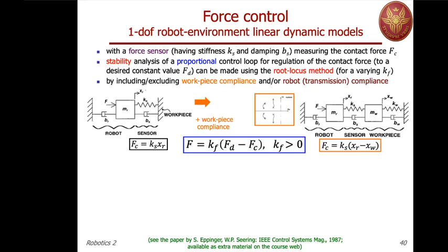So when you're now closing the loop, these four poles, which are all asymptotically stable in the open loop, will move as shown in the root locus diagram, and will remain in the left-hand side of the complex plane, so the system will still be asymptotically stable. Two poles go to infinity along asymptotes, which still remain in the left-hand side of the complex plane, while the other two poles will converge to the open loop zeros. These are standard results in automatic control of linear systems. So even in this case, by increasing the gain kf, you will never capture an instability.